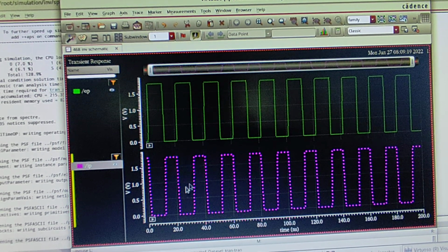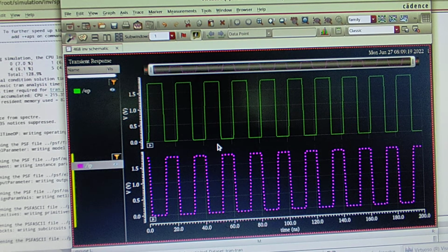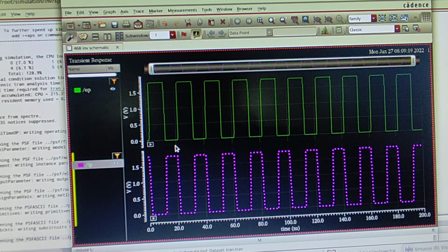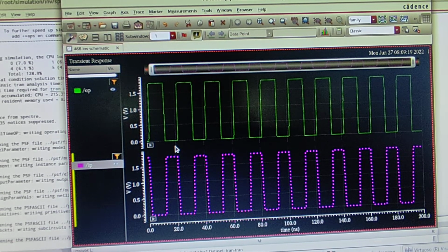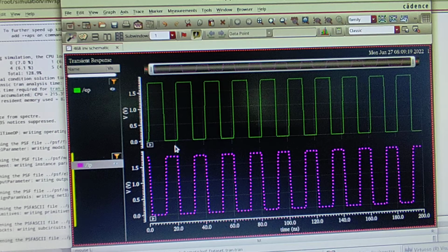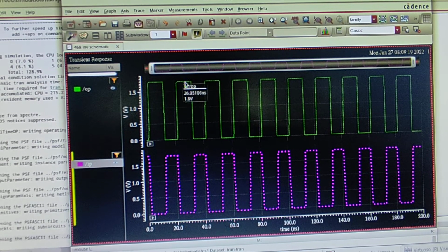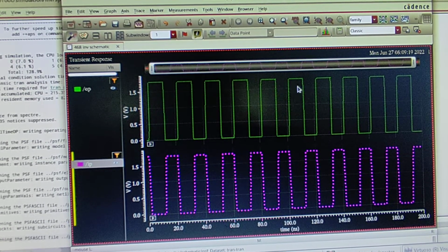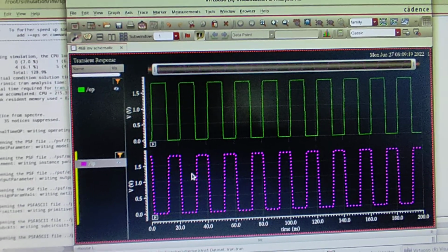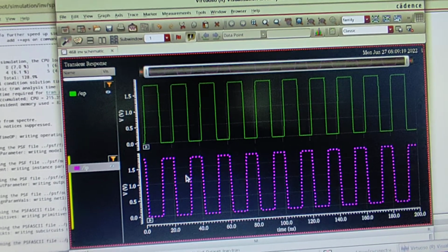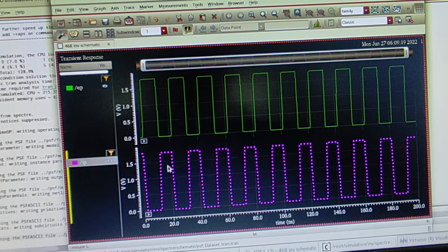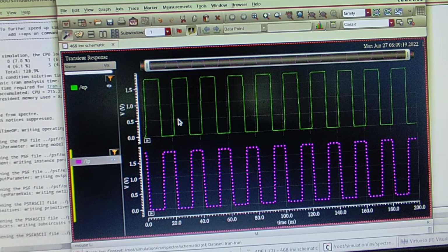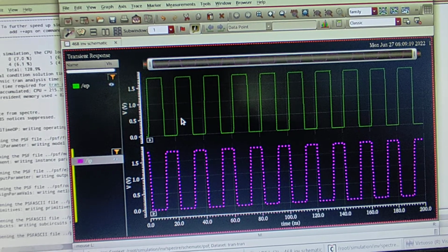So at each interval we are seeing a smaller number of spikes also. If we have the connections clear while making the schematic itself, we can expect very few spikes being generated in this graph. So we don't see any ups and downs, everything is flat here. It's a matter of practice how we connect the schematic using fewer nodes. If we have good connections using wires, we will see less split in the voltage. Right, we need to save this, plot the graph in our records and observations.